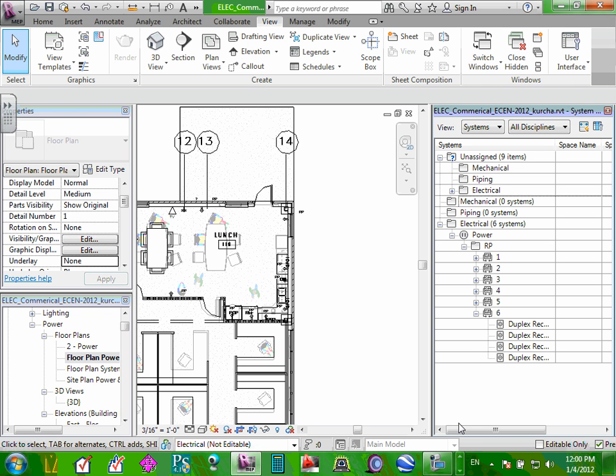It goes in multiples of 6, up to 84. It defaults to 12, but I think we changed the panel to 42 when we came here. If you were here when we put in the panels, we changed our number of single pole circuit breakers to 42. That's a good typical, and then we start adding if we need. Any question, guys, about this?